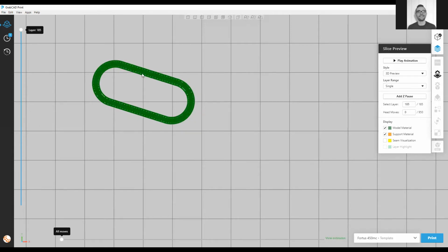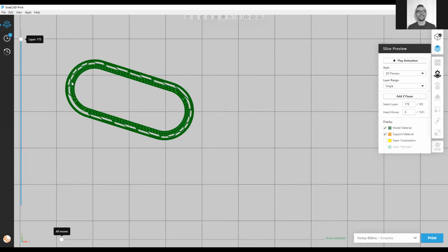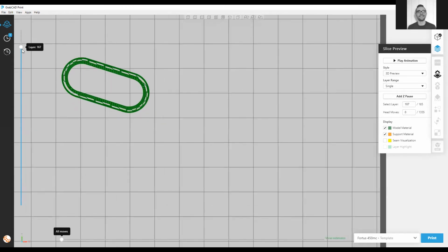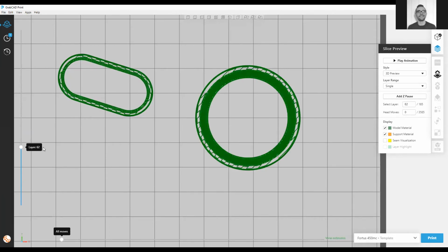Okay, so now that we're finished slicing, we'll start at the top and work our way down. So we can see we're solid, solid, solid, and now we're starting to get into where we've made some adjustments. So we can see the sparse around here with that 100 thou surface reinforcement that we've done. Go down further to the main body, and we can see here again, we've gone ahead and reinforced this inner surface, 200 thou, and we can see how we've optimized that there. It still retained the sparseness on the outside.